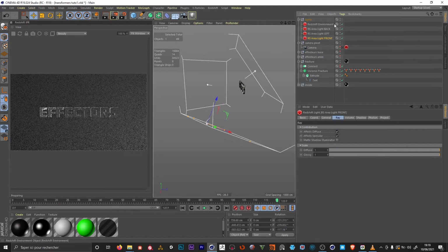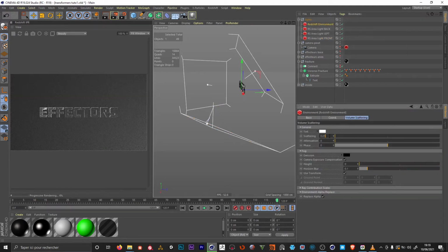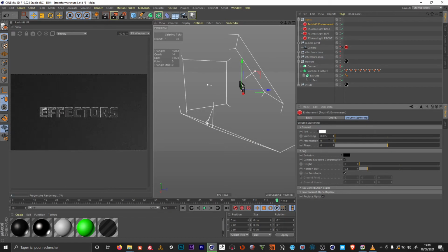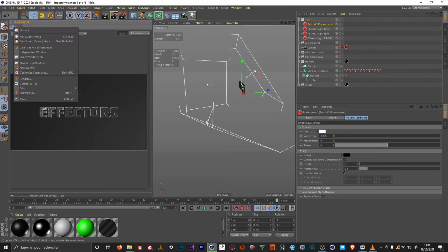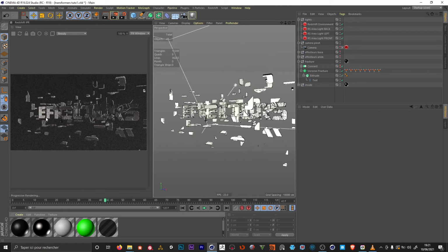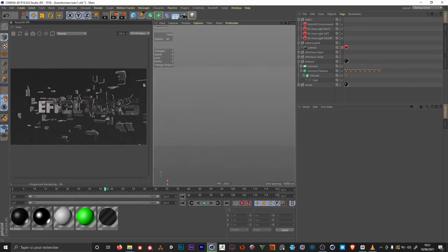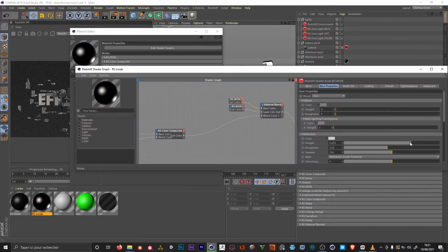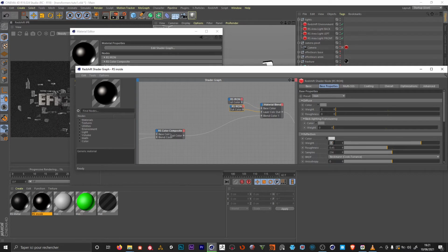I think the volume scattering of the environment is too big. I will try 0.001, which is too little. I'm gonna increase to 0.005. I think the title reads better like that. Compared to what I did in the little demo video, the inside was darker. I'm gonna try to have less reflection on this one. I'm gonna set the weight to 0.5. And this one, I'm gonna set it to 0.3.